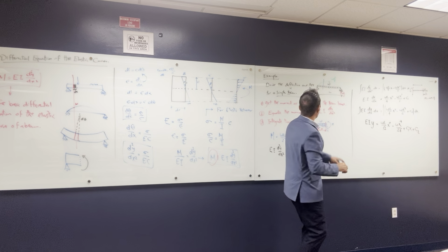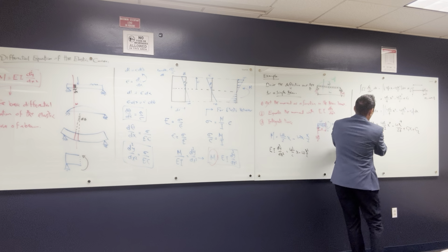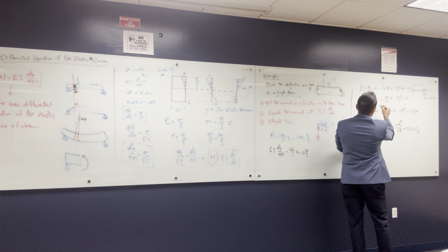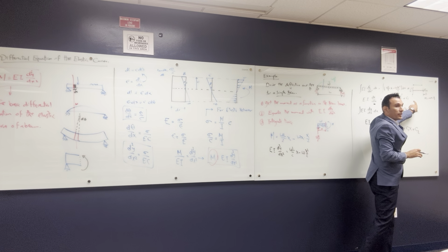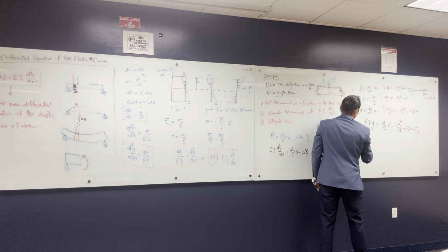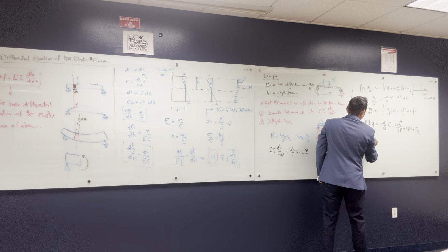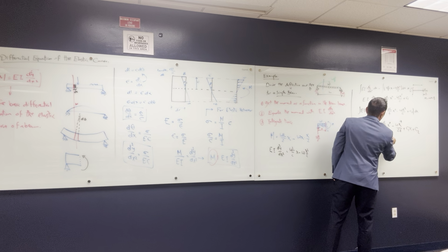So right now I have what he wants. He wants the deflection y and the slope theta. I have y here, and I have theta here. All I have to do is divide by EI. But I still have the constants of integration. I need to find them out. To find the constants of integration...